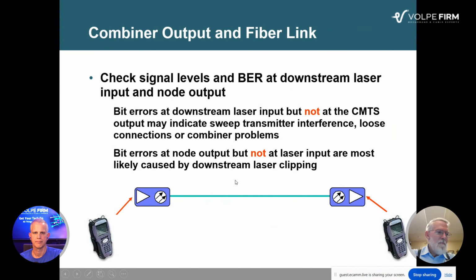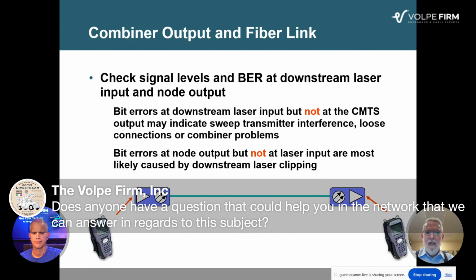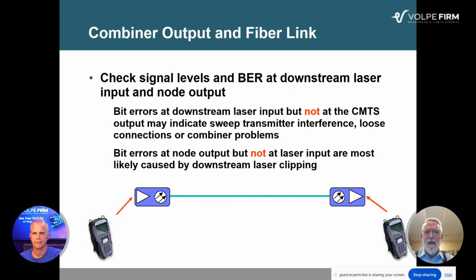When my cable provider launched DOCSIS 3.1 in my node service area several years ago, I hooked up my meter and looked and said, oh, cool, there's the OFDM channel. And I looked at the SC-QAM channels. All of them were red, every one of them. I looked at them, and every one had pre-FEC bit errors. No post-FEC errors, just pre-FEC bit errors. So I suspected maybe a little bit of clipping going on in the laser because the total composite power had increased with the addition of that OFDM channel.